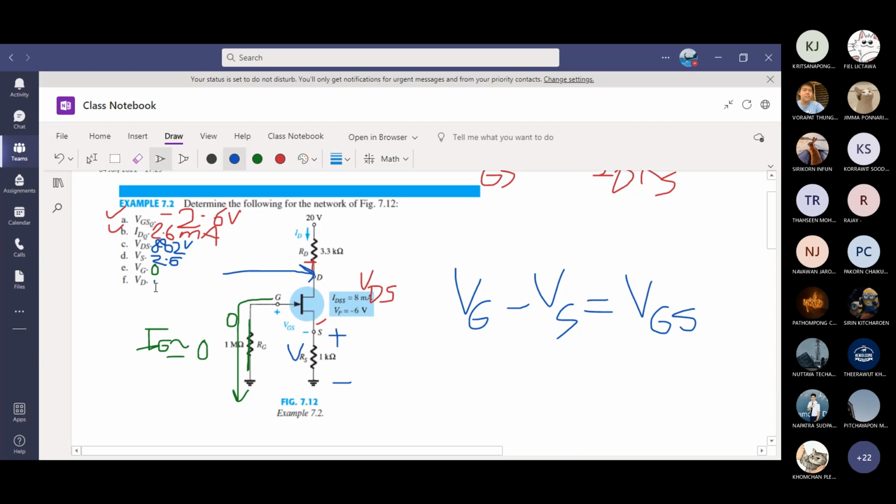Here it will be, I write 11.42 volts. You can verify: 11.42 minus 8.82 minus 2.60. Yes, I just verified the loop. So 11.42 is correct.